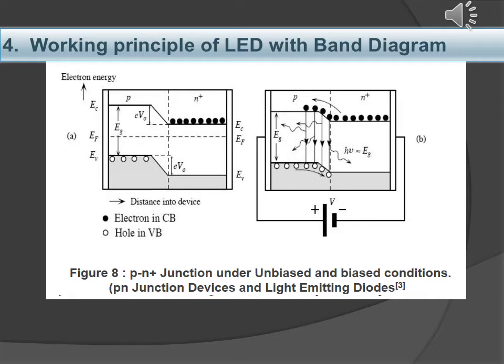Homojunction PN diodes, heterojunction PIN diodes, where the intrinsic layer has a smaller band gap, and PN diodes with a quantum well in the middle are all used for LEDs. We will only consider the PN diode with a quantum well because the analytical analysis is more straightforward.